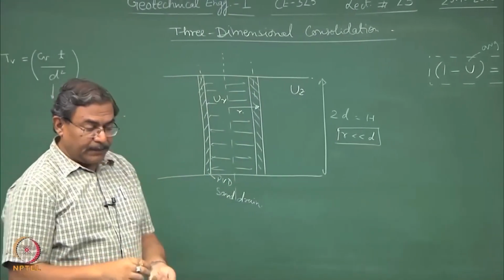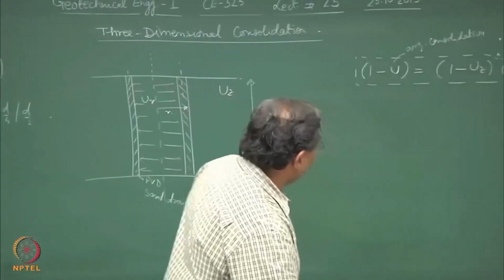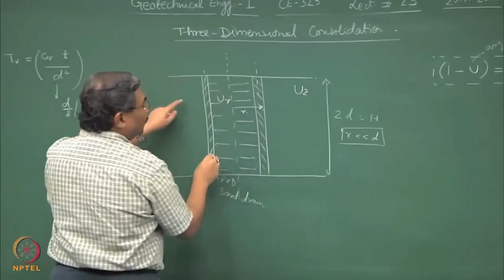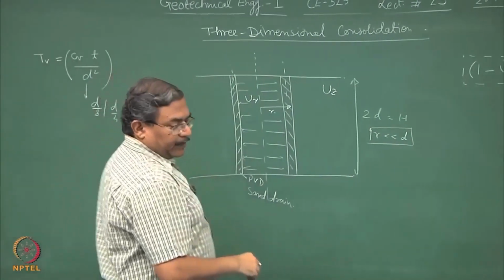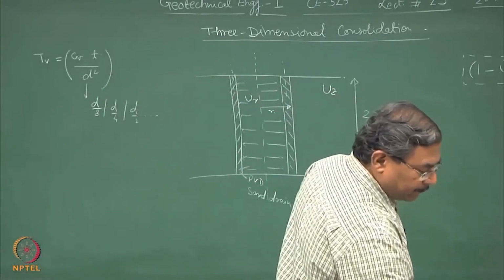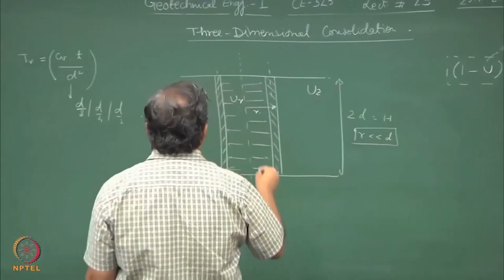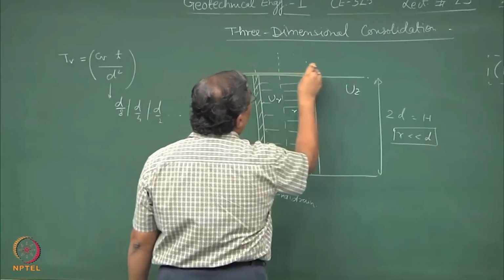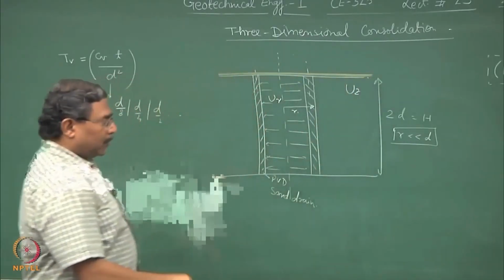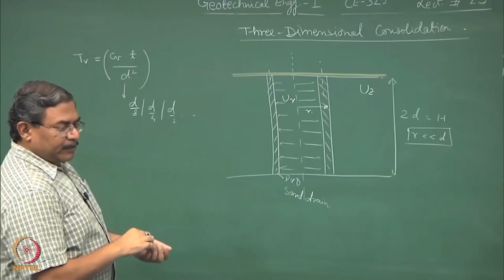The procedure is, having inserted these drains in the ground, we provide a filter layer, and on top of the filter layer we provide a geotextile.